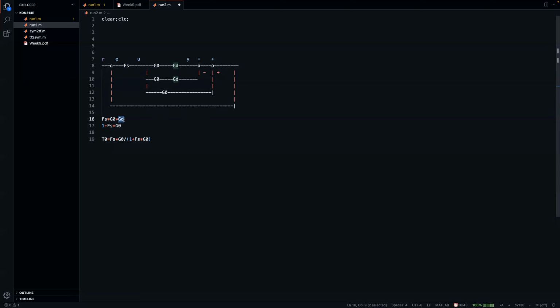The only thing that you cannot prevent from happening is the addition of delay in the feed-forward path. And you're okay with that because there will be delay in the system. The system will react after some dead time or after some delay time. And that's not something that you can prevent at all. So you are going to be happy with that. And during the Bode approximation in the previous question, when we had the step response, you've seen that there's 2 seconds delay in the closed loop step response anyway. So this structure handles the delay part. You're focusing on the non-delay part, designing your controller, plug it in, and you're good to go.